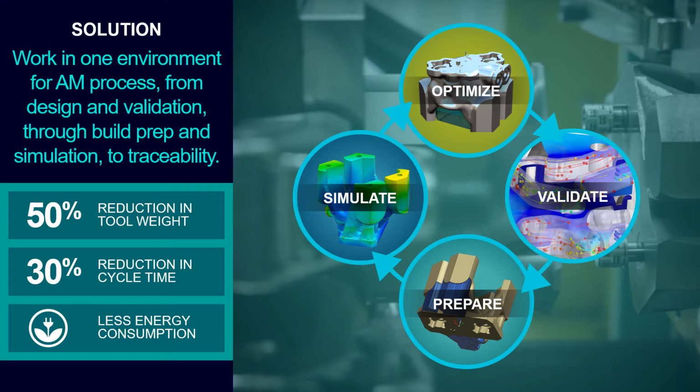If you remember the chart I showed earlier, the cool down time takes the majority of the time in a mold cycle. This means that it is ripe for finding new areas of efficiency. Now, Toolcraft was also able to cut some of the mass of the mold almost in half, which significantly reduced the energy consumption of the mold process by utilizing other advantages of additive manufacturing like lightweighting.